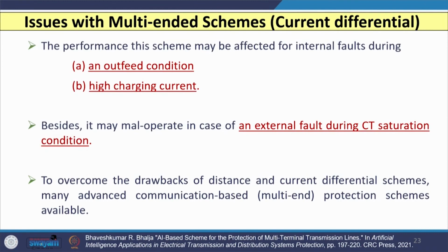However, there are some issues faced by the current differential scheme. The performance of this current differential relay is affected in case of internal fault, particularly when there is an outfeed condition and when high charging currents are there. Moreover, in case of external fault with CT saturation, this relay may maloperate.